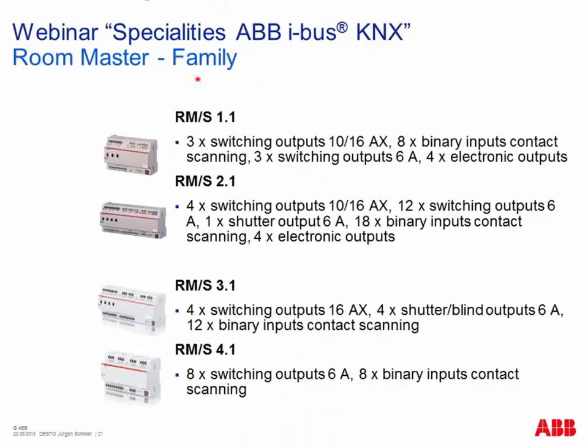Yeah, and if you look at the whole family of room master, there are 4 in total. The first 2 are mainly created for hotel rooms, including also room temperature control outputs. The other two are more for classical apartments, let's say, with inputs and outputs, either for operating circuits or sockets, or also for motor control of shutters and blinds. So you see different combinations of inputs and outputs in these devices, but the concept is always the same. Internal connections are possible, and in principle, room solutions or apartment solutions.